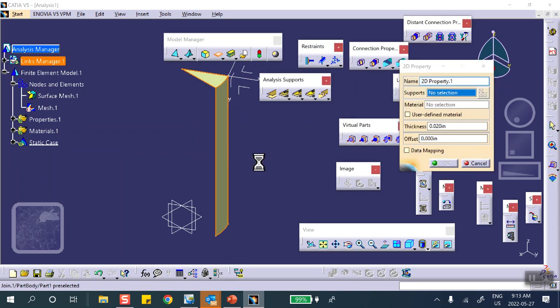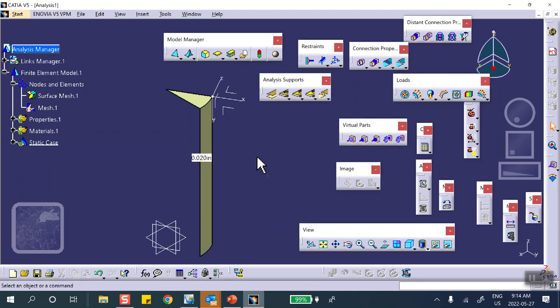Thickness on that face, whatever it is, 0.02, 0.2, whatever. Just remember that these formulas that I wrote down for you are valid for thin wall pressure vessel. So if you want to check against those formulas, this better be small thickness. I mean, in principle, you can make it 1,000,000 miles, it'll do it for you. It's garbage, basically. So all I'm saying is that we go ahead and recklessly do this thing.